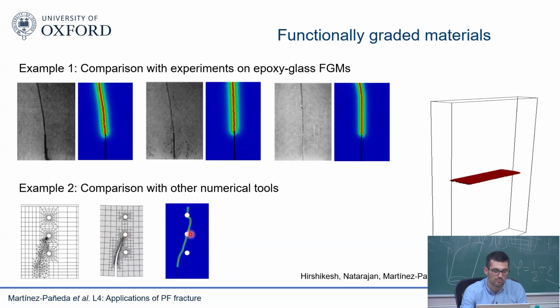Phase field has the ability to predict the nucleation of a crack. So you keep loading, a crack appears there, the crack continues to grow, eventually the crack reaches the third hole, then you keep loading, a third crack appears, and then you get the complete failure of the specimen. So different to these other methods, whenever the crack reaches the hole, the calculation is at an end. We have the ability to predict the nucleation of cracks from smooth areas, like here, and then you can grow the propagation of the crack. So I think this is another classic example. But basically, this is the idea.